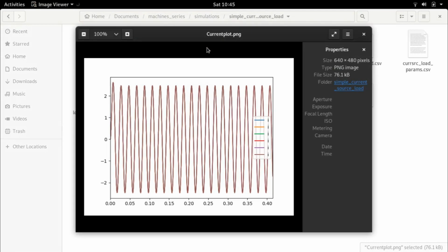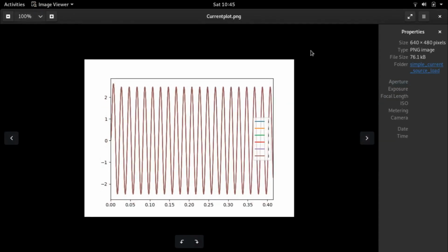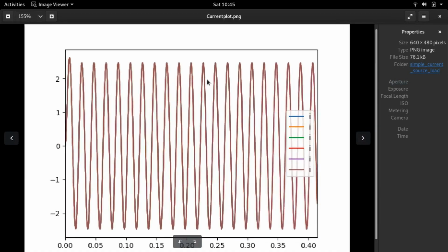Let's hope finally I have a simple plot. This is something else. I think this is something to do with the operating system. I can't understand it. But what's important to understand is even though it looks messy, we now have an RL load emulation. This is emulating an RL load. Now this RL load, if you really compare, has exactly the same dynamics as would happen with a resistive inductive combination. Right? It has an initial transient.